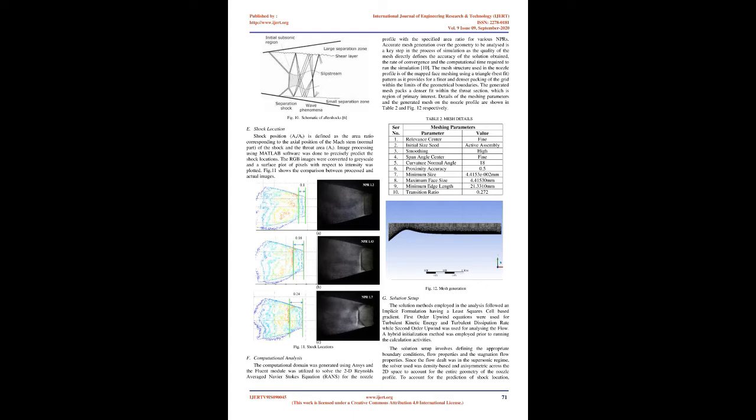Even though the flow behind the Mach disk is subsonic, the wavy slipstream, with convergent-divergent shape, causes the subsonic flow to accelerate. The local sonic throats created by the slipstream ensure supersonic flow downstream. The reflected shock, after impinging on the shear layer, reflects back as expansion fans, thus causing the supersonic flow downstream to further accelerate. These expansion fans, whilst getting reflected from the shear layer and jet boundary, reflect as weak oblique shocks, and these appear as aftershocks. The aftershocks are predominantly straight, thereby indicating that the flow downstream is more or less uniform in nature. Fig 10. Schematic of aftershocks.